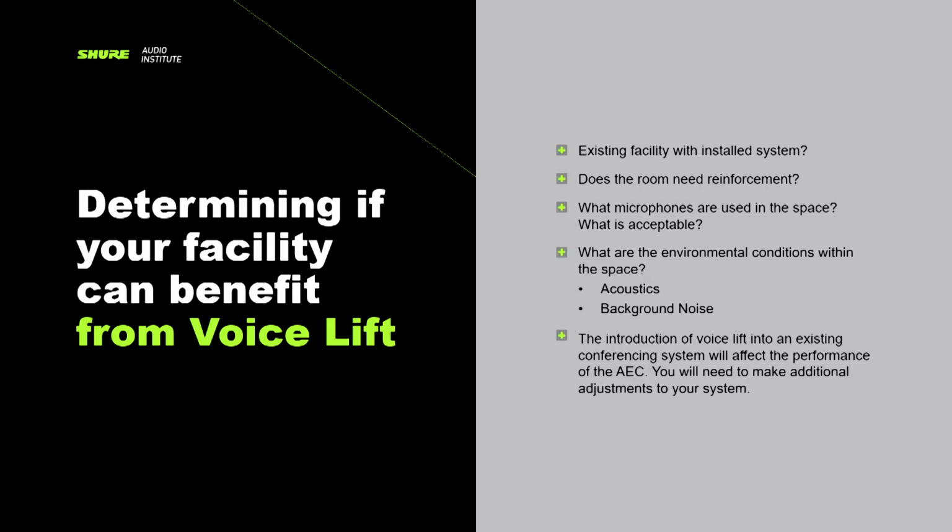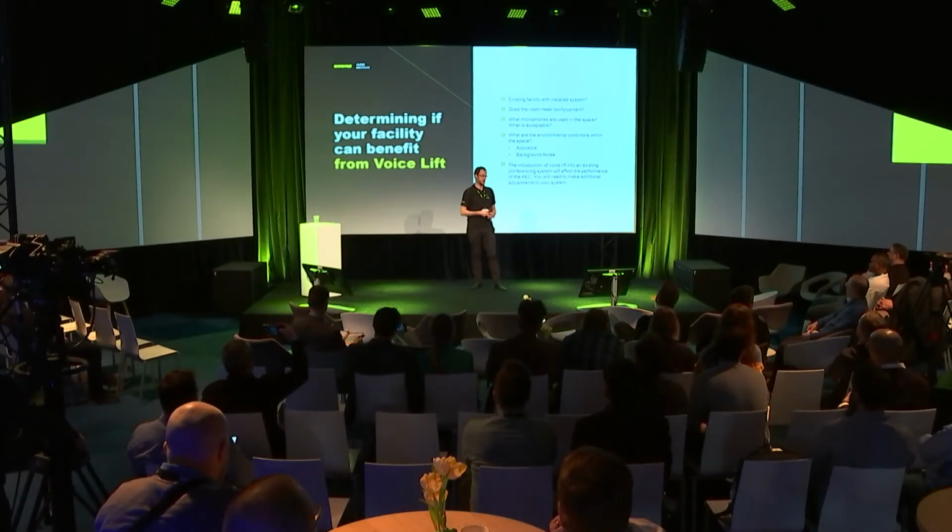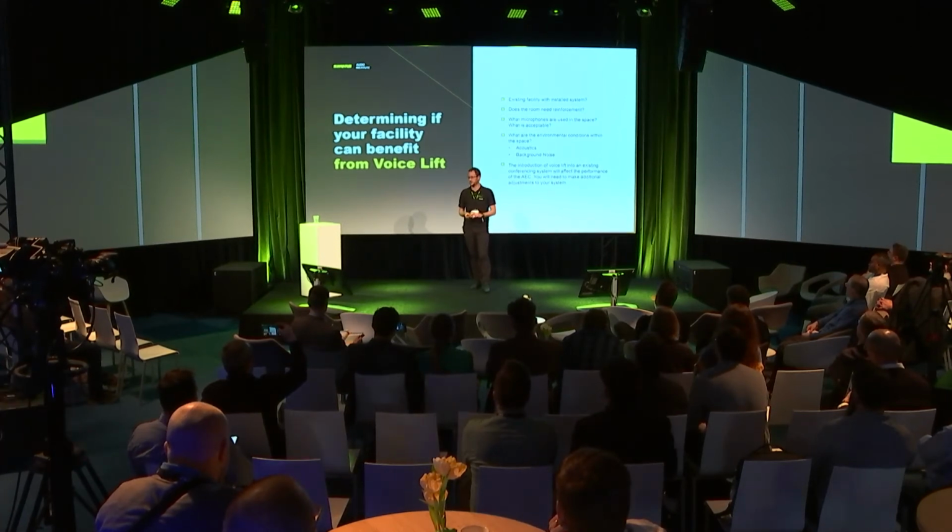So the introduction of voice lift into existing conferencing systems will affect the performance of the acoustic echo cancellation processes. So you might or probably will need to make some adjustments for that introduction of extra signal into the loudspeakers.